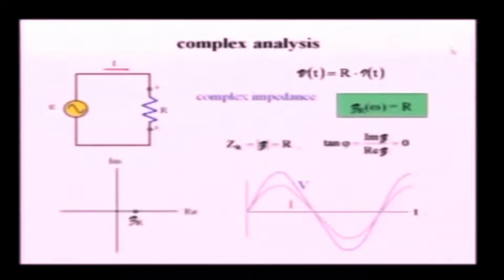All right, let's now draw the two phasors. Yeah, so let's say at this instant. And again, I already skipped drawing the circle. But first of all, in principle, I should draw a circle with radius equal to the peak value of the current, and draw a horizontal line and find where the horizontal line crosses the circle, and select one which corresponds to the rising current. I skipped that. I hope that you already comprehended it.